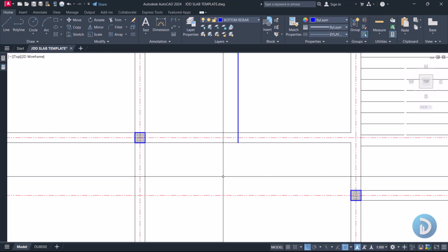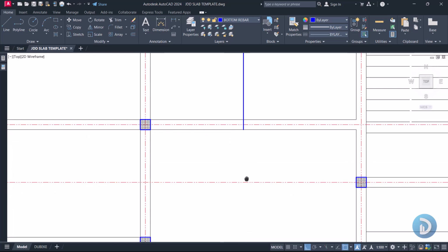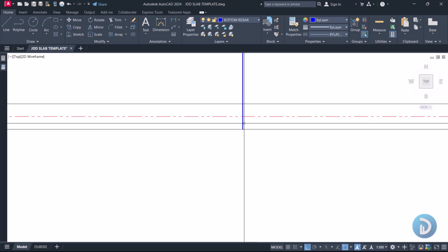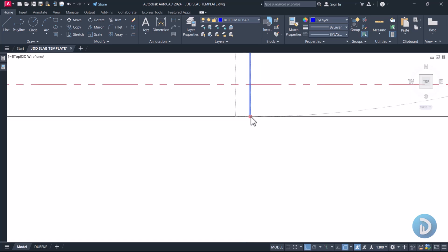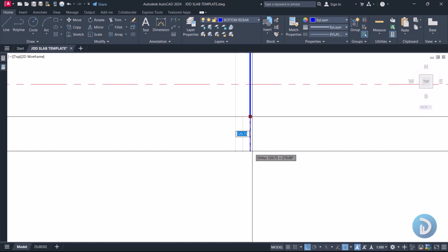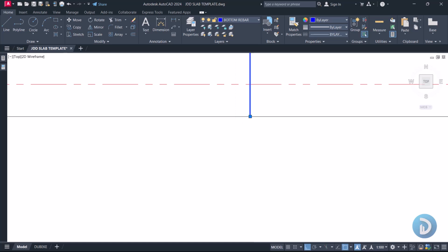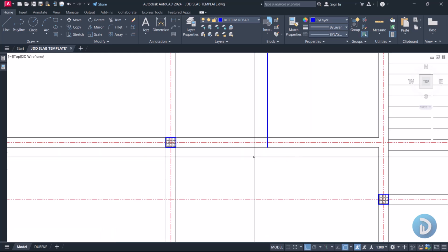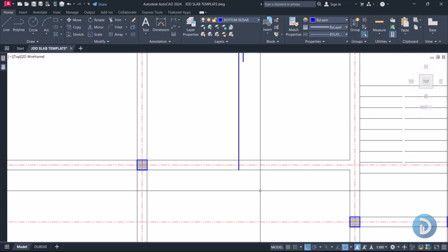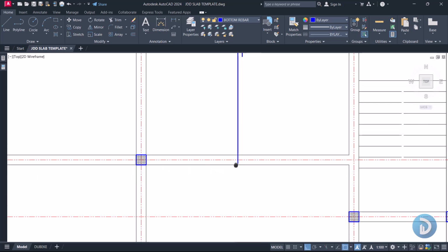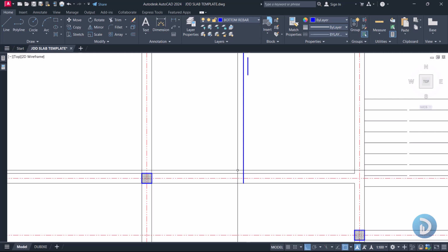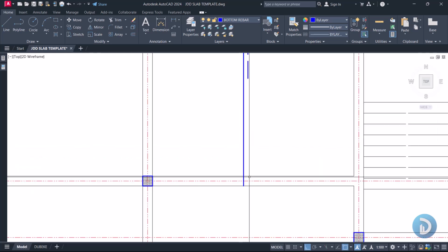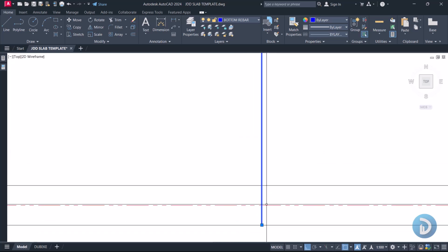So at this other end we have a continuous slab, and due to this fact of having a continuous slab, we don't necessarily need to return this reinforcement 25 millimeter into this beam. As a matter of fact, we can choose to increase the length of this reinforcement by, let's say, a minimum of 150 millimeter, and this is not necessarily to counter moments at this point, but to enhance the connectivity between our slab reinforcement and our beam reinforcement, because our reinforcement is a ductile material. So if during casting process, while they are stepping on this reinforcement, this length can choose to retract.